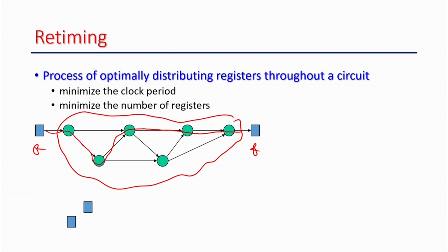And what we can do here, by retiming we can move these registers inside the circuit, right. Suppose I want to remove this register from here, I want to move it inside. When you move it inside, it has to be placed on all the fan outs, so it will be placed here and here. Because this just reduces the delay by 1, we still have 4. So, I can move this register again.